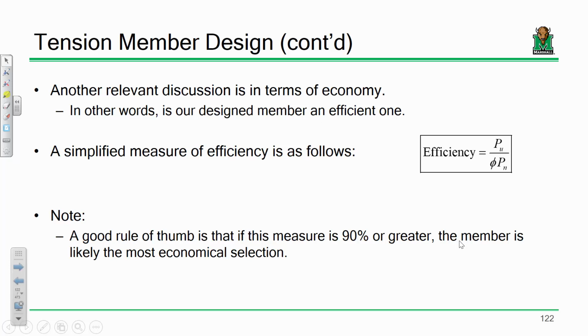Also, another thing is if you're connecting this tension member to adjacent parts of the building, having those members have similar depths makes the connection very doable. Like, what if I have a W10 section? So let's say that's a W10. These are the flanges sticking out, and that's the web. And I'm trying to connect that to a W27. How do I connect those two? That's kind of weird, right?